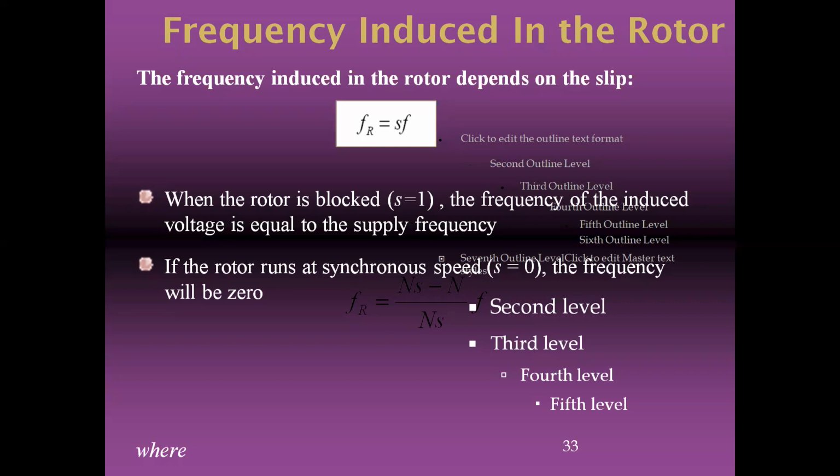Similar to the induction motor, the transformer secondary would also start to rotate, but it does not. Why? Because in a transformer, primary and secondary are mounted on the same core. Here, the stator core is different, the rotor core is different, and there is an air gap between them. In a transformer, no air gap.